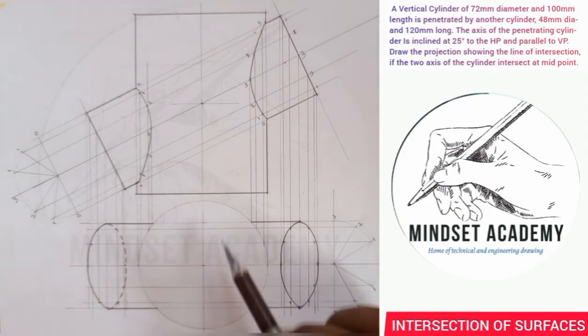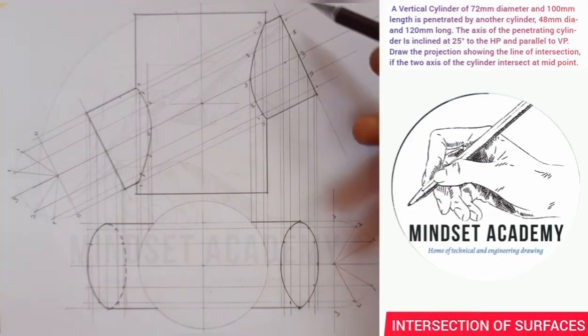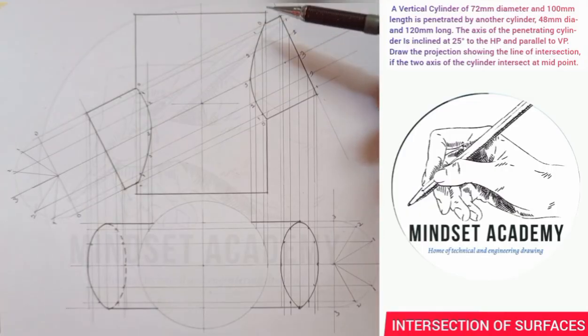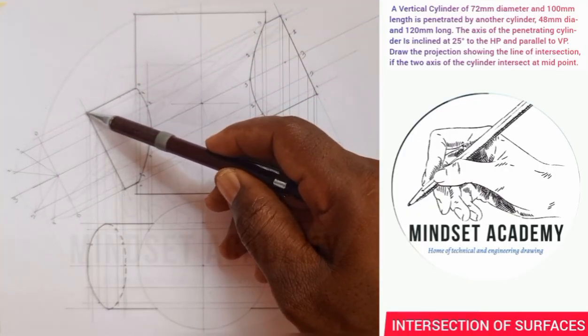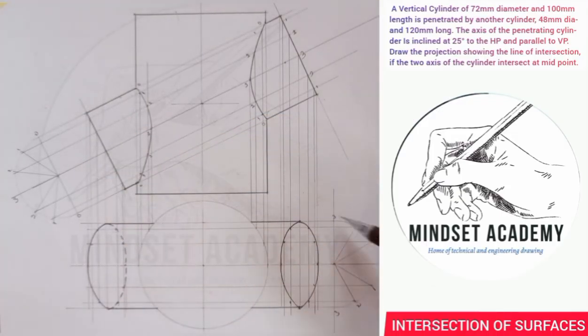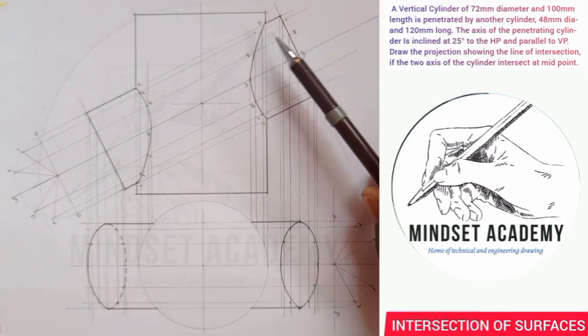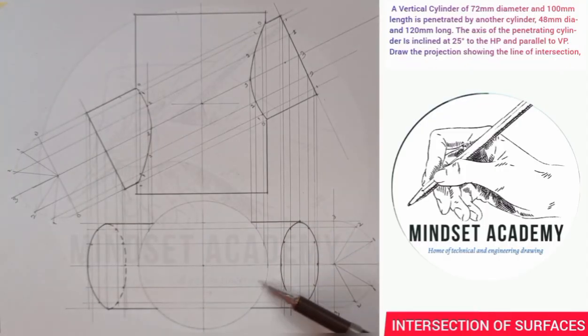This is the interpenetrating arc of this cylinder here. In different cases, you can see these two, you cannot see this. We are looking from the top. So looking from the top, this will be visible, but this you can't see because it will be hidden. So this is what we have successfully accomplished by drawing the intersection of these two solids, drawing the interpenetrating arc, and also drawing the complete plan of it.